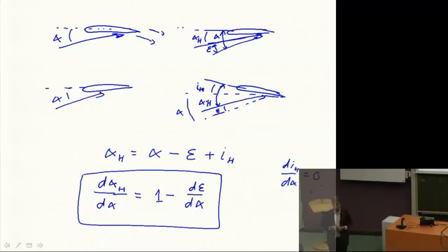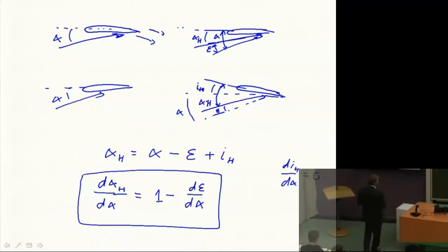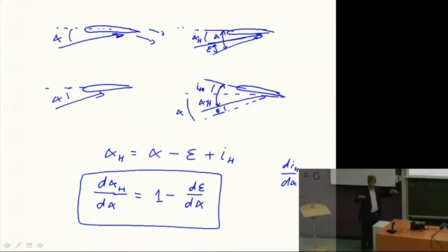Why do you say that the IH alpha? That is because the IH is nothing else than the angle that the pilot has set the horizontal surface to with his trimming wheel to get an equilibrium without having to pull the control column all the time.